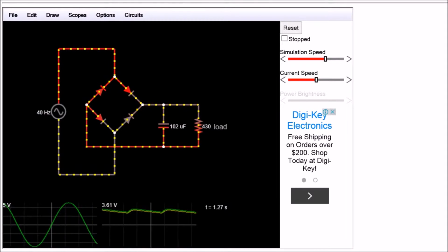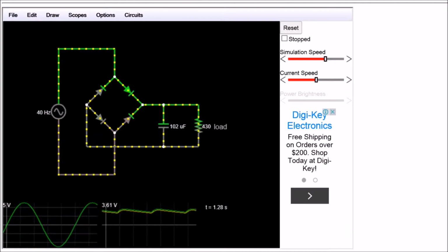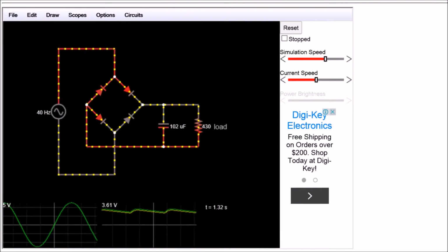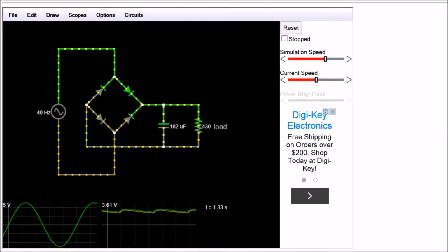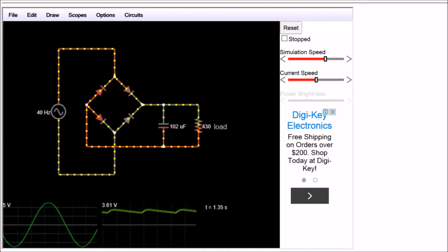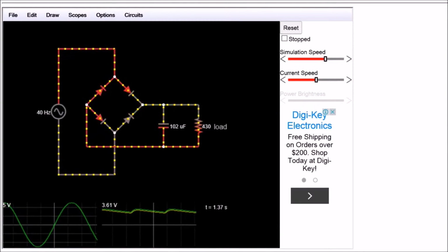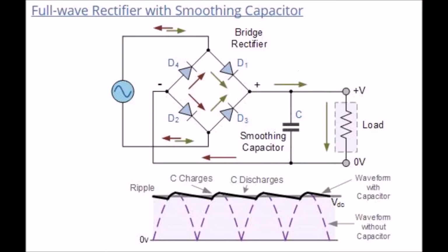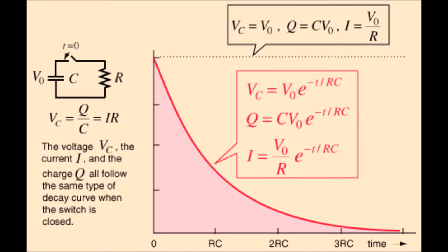Capacitors are also commonly used in three-phase and single-phase rectifiers, whereby the capacitor is used in parallel with the output to create a smooth and continuous DC output voltage that is compatible and suitable for electronic equipment, such as mobile phones within the mobile phone chargers and battery chargers. In all these applications, we are required to know the characteristics of each capacitor and be able to predict the voltage, charge, and more importantly, the rate and time taken to charge the capacitor to saturation.